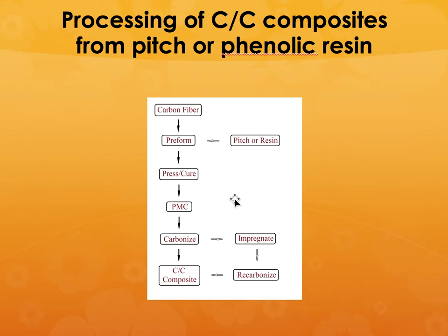So one of the special types of composite materials is carbon-carbon. I don't know if you know this or not. Some of the earliest successes of the space shuttle program were because of the capability of carbon-carbon composite materials. These are made by a specific type of process, and are also being used in missile nozzles and so on. The carbon fiber may not be continuous, or they could also be continuous fibers.